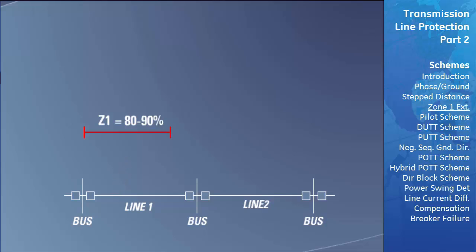If the fault was transient in nature, the first occurrence of tripping the line would have removed the fault and transmission of power would resume. If the fault that occurred was a permanent fault and reappeared after the reclosing, but was not located in the new shortened Zone 1 protected area, the relay would not pick this up for a second time in Zone 1 and not trip to try to clear the fault. The permanent fault would then be cleared by the Zone 2 protection after the set time delay if the fault fell inside the transmission line's end zone area.